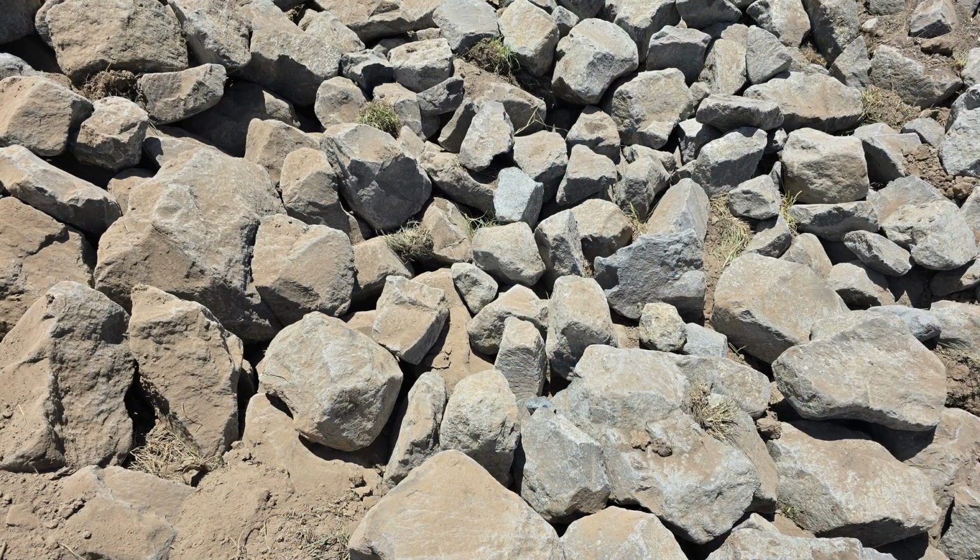This rock is too clean to use in armoring a slope or building a vertical grade control structure. It would be better if smaller diameter rocks and fines were mixed in along with soil so water would not flow between the rocks and cause erosion.